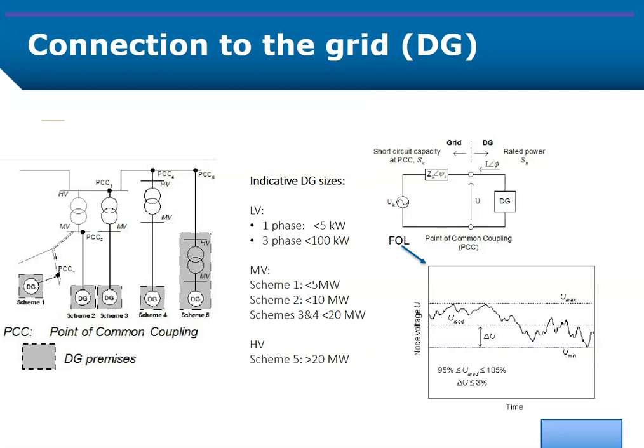The connection point of the DG station, on the other hand, is the actual point of coupling to the network, which is located at the terminals of the DG station. The significance of the PCC is that the power quality related technical criteria are mainly evaluated at this node, rather than at the DG station terminals. The physical interface between the DG installation and the network is the coupling substation, which includes the energy metering arrangements and the necessary switch and protection gear, typically.